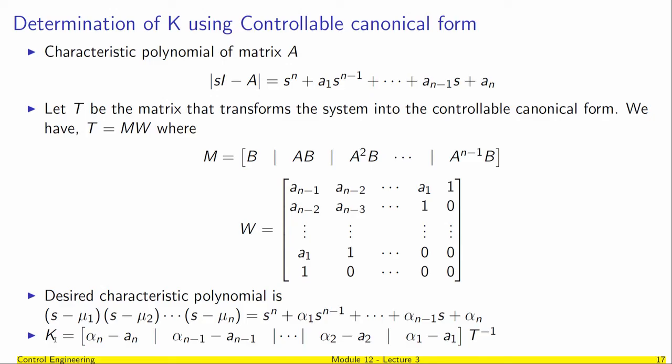So, what we have seen in this lecture is the definition of controllability to check if the system is completely controllable or not, and if it is, how to do the control law. The only control technique we have learnt here is pole placement. There are other formulas, typically called Ackermann's formula. I will skip those details, but what is important is to know the concept, and once you know it, even Ackermann's formula is quite easy to derive. You could also directly ask MATLAB to compute the gain matrix K for you, but before you do, it is very advantageous to know the procedure to compute the gain K.